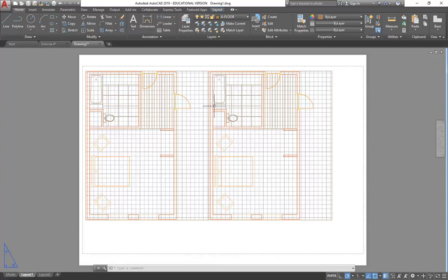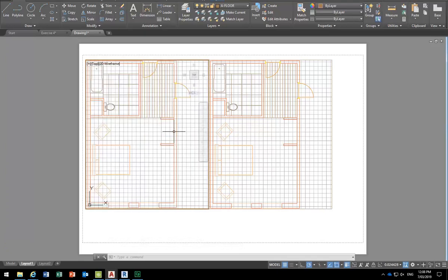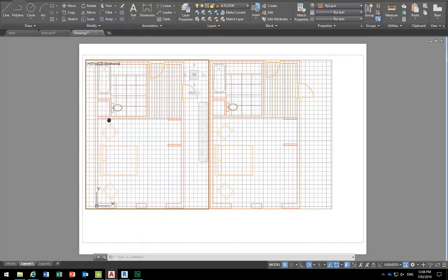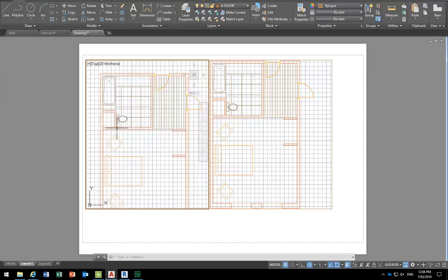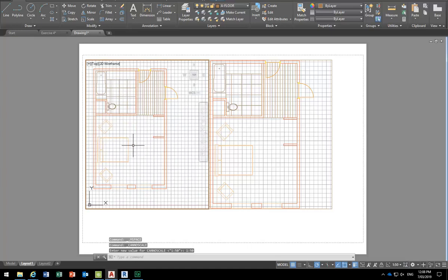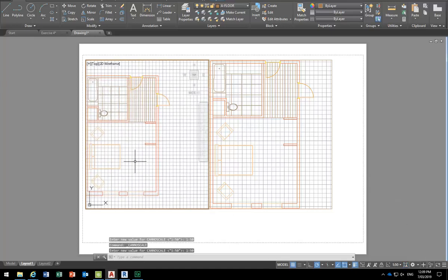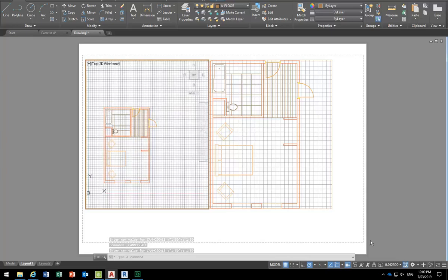So I've got my 2 viewports. If you remember, you can go to model either by clicking on that button or just double clicking to make it active. Now when I zoom with the wheel, it's only going to zoom in that viewport. But I'm not going to set the size by zooming. Of course, that changes the view or the zoom. But when you set the scale here to 1 to 50, that makes it accurate. But then, remember, if you zoom having done that, the scale is changing. So you've got to be careful. Once you've set the scale, you generally don't want to zoom, because zooming is the same as scale.